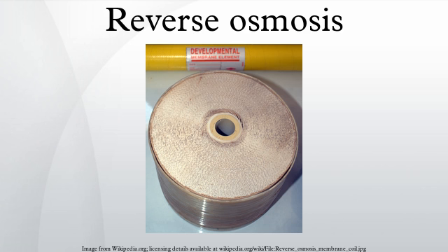Energy recovery. Energy recovery can reduce energy consumption by 50% or more. Much of the high-pressure pump input energy can be recovered from the concentrate flow, and the increasing efficiency of energy recovery devices has greatly reduced the energy needs of reverse osmosis desalination.